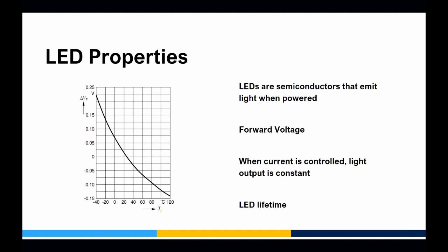That being said, another benefit of having a controller or an internal driver is the ability to change not necessarily the LED lifetime, but the lifetime of your light itself. So if we set up our machine vision system and we set the intensity of our light to 80%, and that's still giving us a good image that's bright enough, over time our image is going to start getting darker and darker, and eventually we're going to have to improve the intensity. So we can just go from 80% intensity to 90% intensity, and that's going to continue to give us a good image.